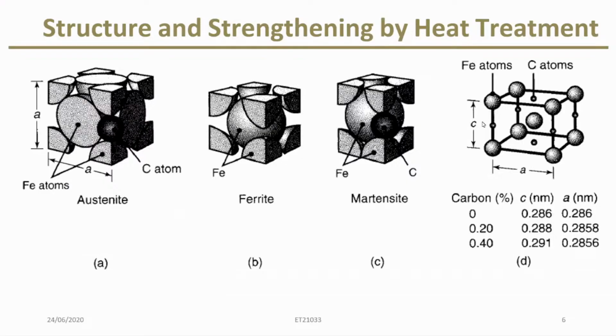So it is ductile and can dissolve a lot more carbon than ferrite. We get it by heating steel above the critical temperature. We hold long enough for the whole cross section to become uniform austenite. Grain size matters: fine austenite grains can produce finer products after transformation, and those products have better toughness.